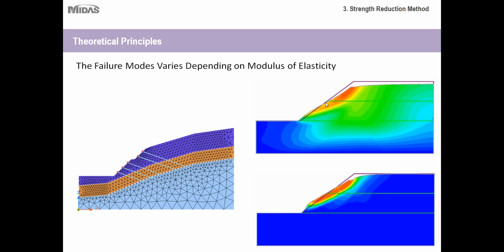So maximum deformation occurs here, sort of along the face of the slope. But it also occurs significantly in the areas beyond the slope as well, or further away from the slope. But in this model here, the modulus of elasticity is much higher, so the materials anywhere are more resilient. So once again, deformation now only occurs near the base of the slope here. So that's just a visual example of how much the modulus of elasticity can alter your results.